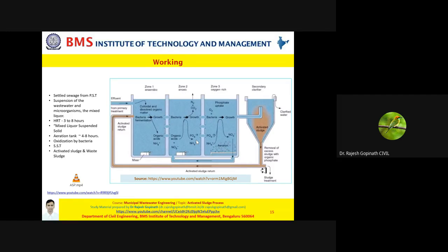Please remember, the suspended solids are not being allowed to settle down in this tank because of the aeration mechanism. The waste impurities, the colloidal solids, dissolved solids, the organic fraction, are always suspended in the wastewater. This facilitates the breakdown of these by the microorganisms, that is your bacteria, your filamentous bacteria, and eventually they help in the formation of flocs.